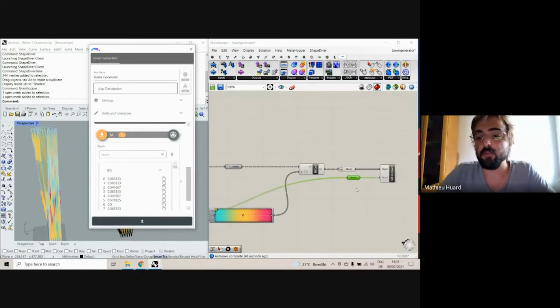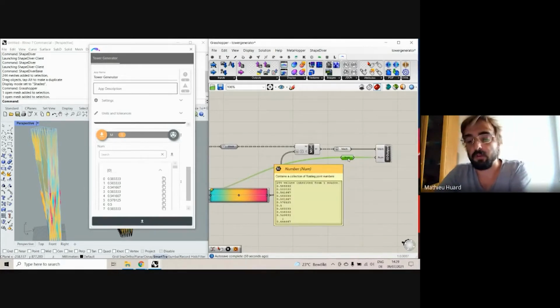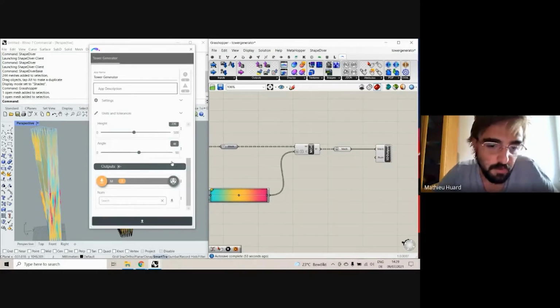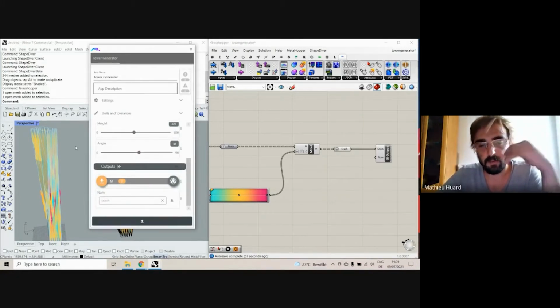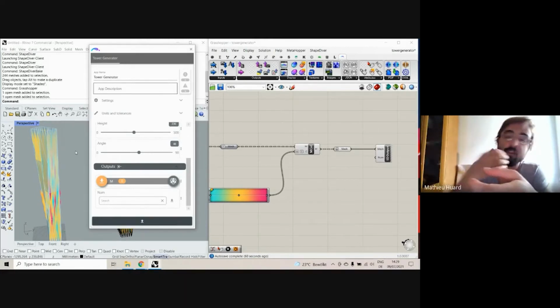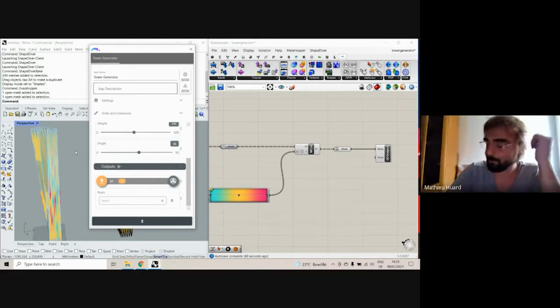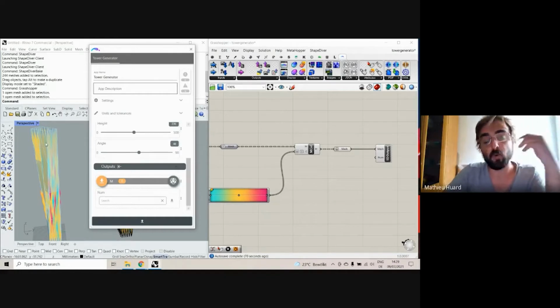So a better way to do this, as I'm sure some of you have already thought or already work in Rhino, is to attach user text, for example. So each panel has a user text attached to it, and then it's stored. So it becomes enriched geometry, right? And Rhino stores this metadata as user text. There are other types of metadata in geometry, but user text is usually what you use if you want to store some numerical value for each panel, let's say.